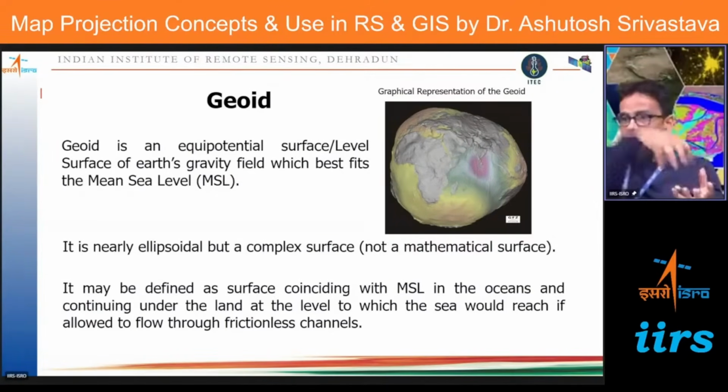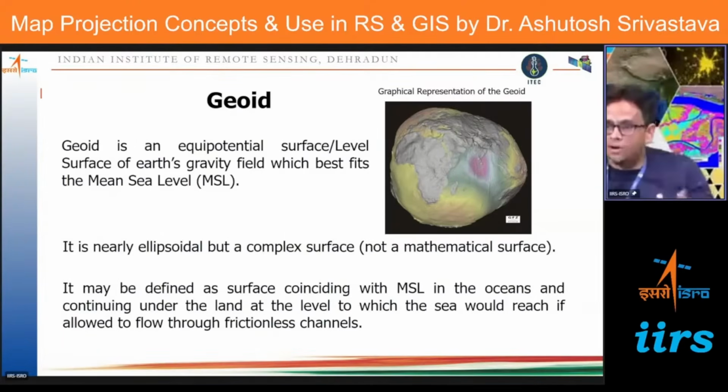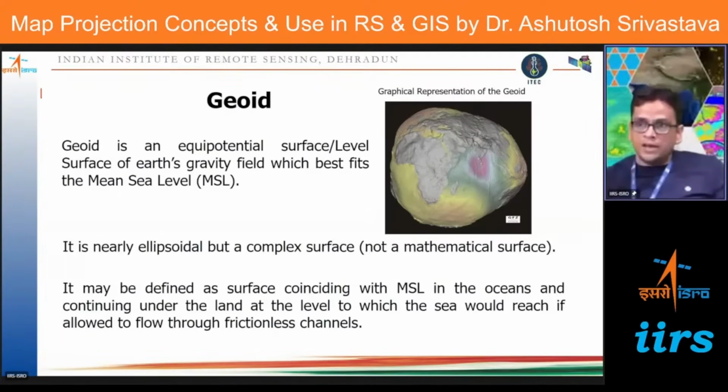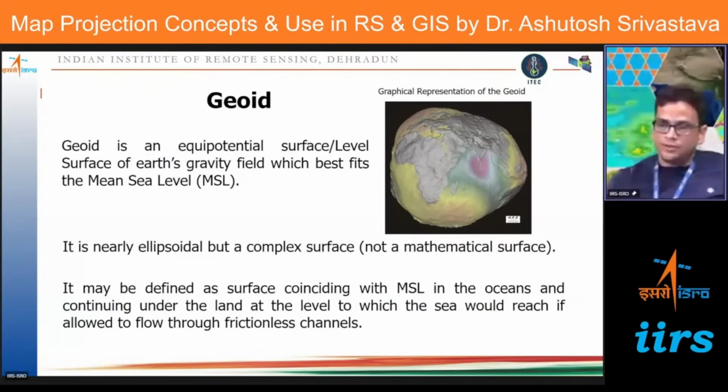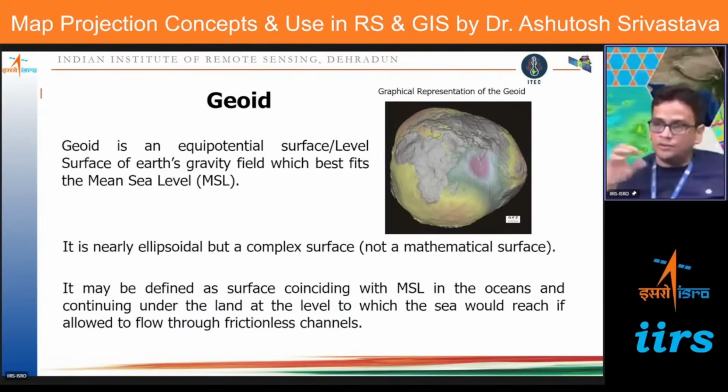From there, we attach information onto this ellipsoid and make it more real, like the Earth, and that is called a datum. Today we have WGS 84 and GRS 80, all geocentric ellipsoids or datums. Now, latitude and longitude we can derive onto this datum or ellipsoid.